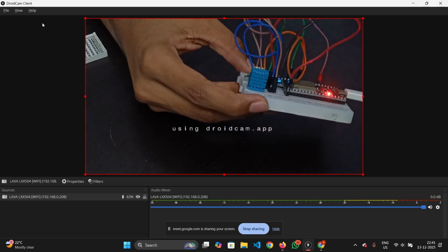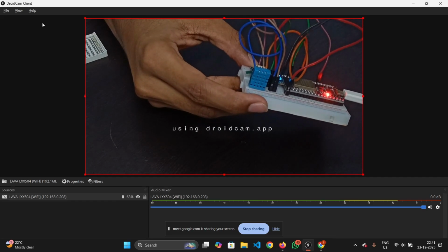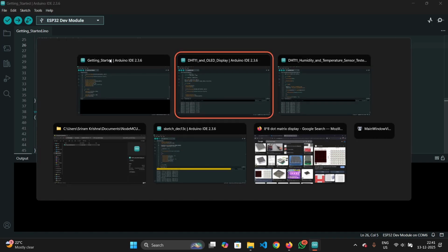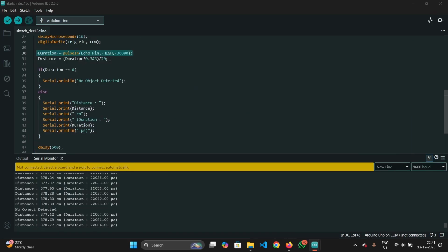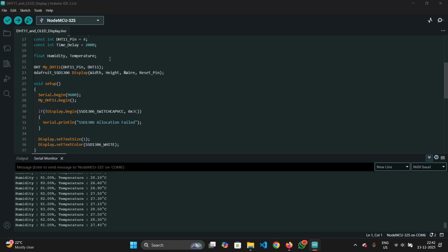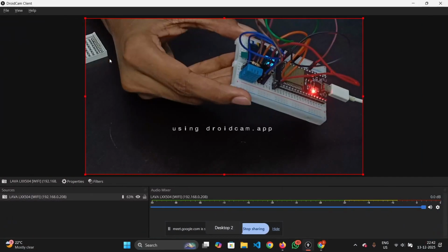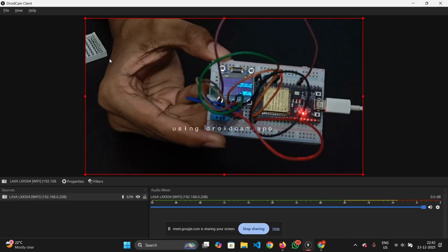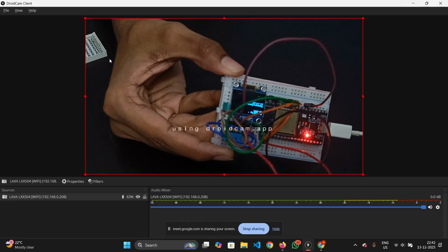Now, using this DHT11 sensor, I'm reading the humidity and temperature of the room, and as you can see, my serial monitor receives the temperature and humidity here. I went through a website which told me how to use an OLED display yesterday and today. I had this lying around but never actually used it. So I finally learned how to use OLED displays yesterday. Basically, I'm printing my temperature and humidity on this right now.